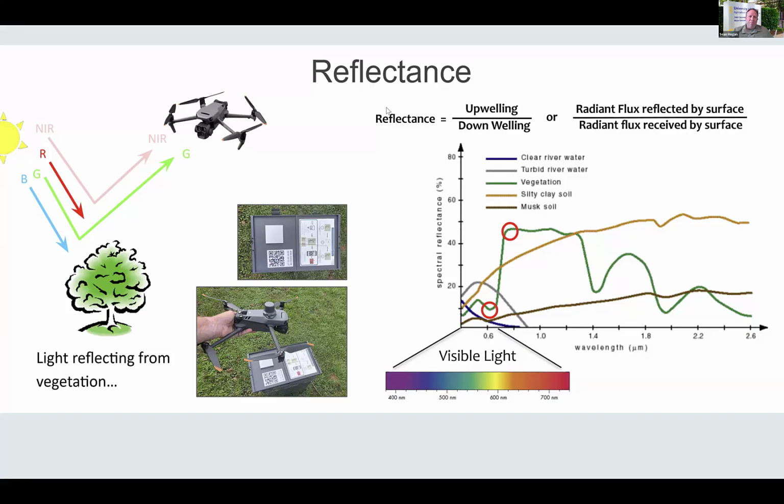You'll see shortly. Reflectance. This is one other thing that I love that Drone2Map does now: you can use a drone, in this case a Mavic 3 Multispectral Pro, over a calibration panel, and I can calculate for reflectance. That's important if you want to scientifically study your data.